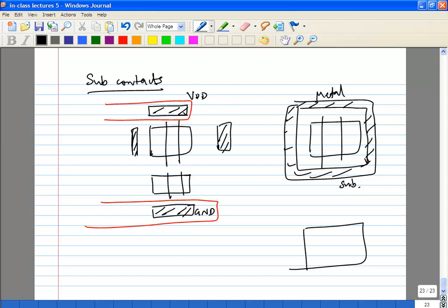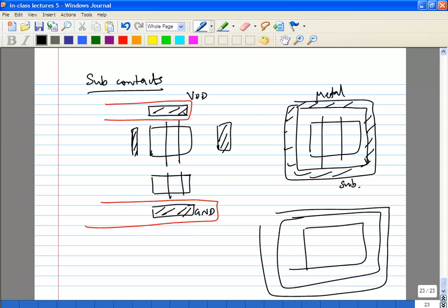Around your overall circuit, it's actually not uncommon to put what is called a guard ring, okay. So the main idea is, let us say there is a noisy block right next to this block, and which is injecting something into the substrate. So you want to pick it up before it reaches your sensitive circuit. So in that case you would put something like a guard ring, okay.